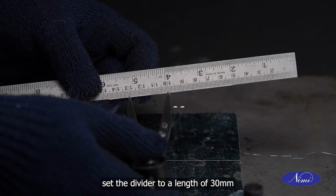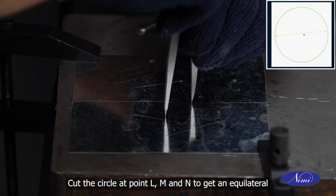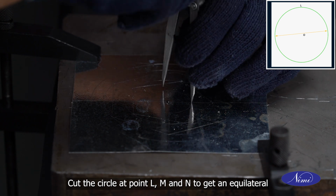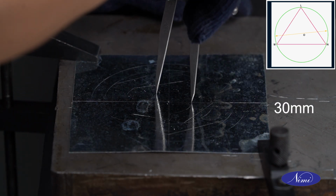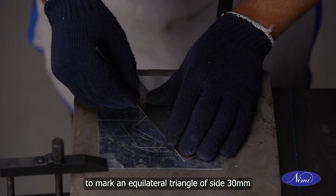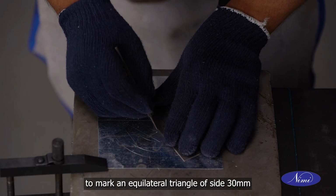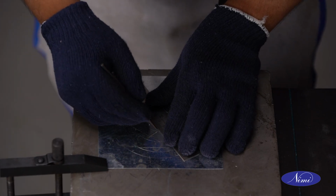Set the divider to a length of 30 mm using a steel rule. Cut the circle at point L, M and N to get an equilateral triangle of side 30 mm. Join the points L, M and N to mark an equilateral triangle of side 30 mm using a steel rule and scriber.